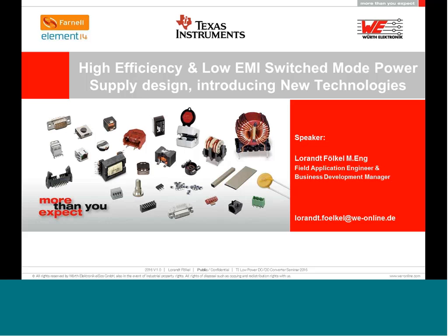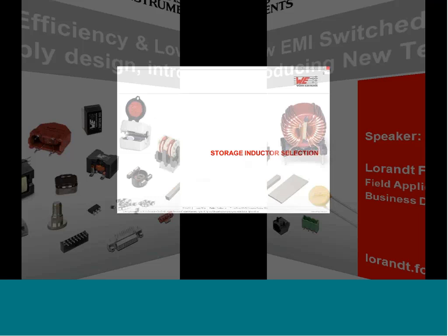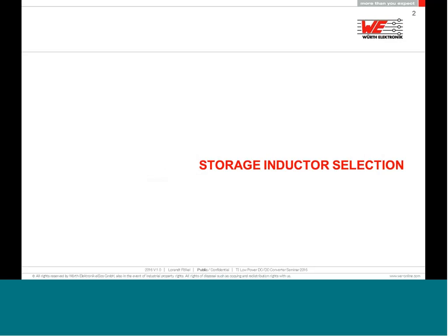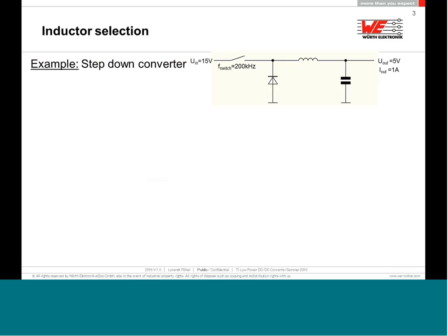Session about efficiency: how to make a power supply efficient, how to choose the right inductor, and how to calculate the inductor according to the efficiency. First of all, when you think about selecting a storage inductor, it's very important that you know whether you are working on a step down, step up, or buck-boost converter.